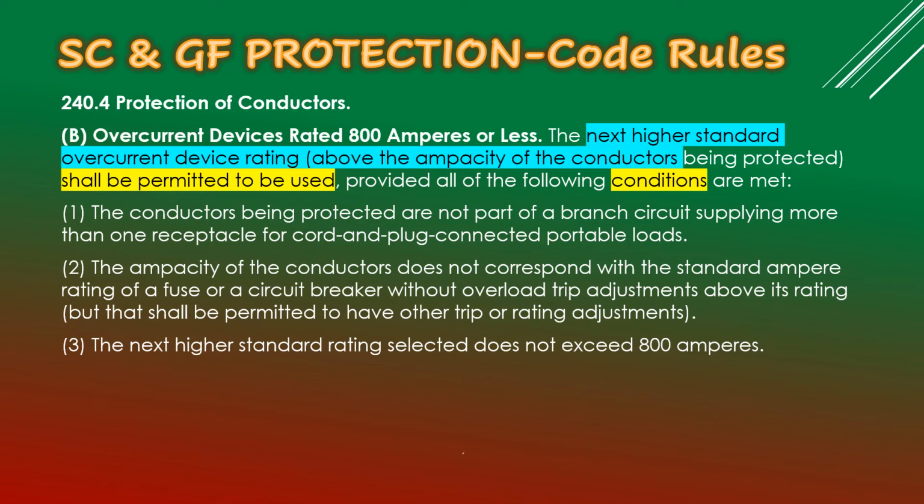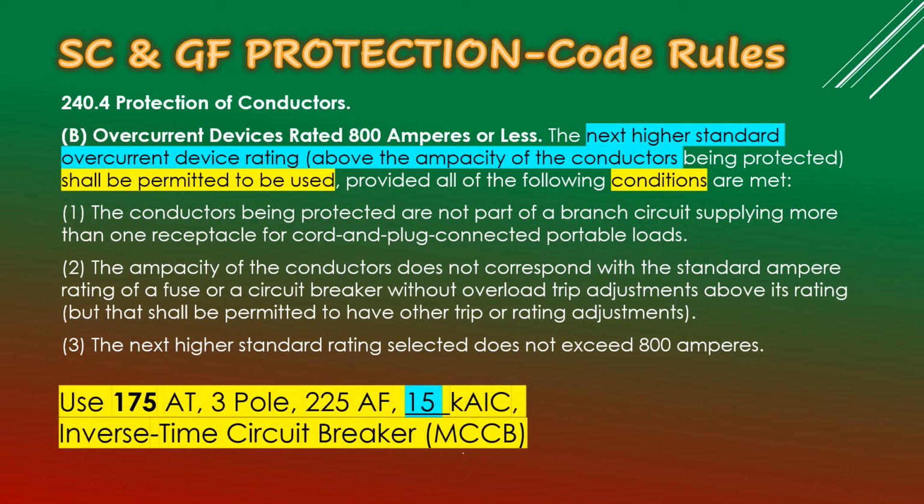So this also we comply because our current is only 165, not exceeding 800 amperes. So therefore we can use 175 ampere trip because our circuit is safe.